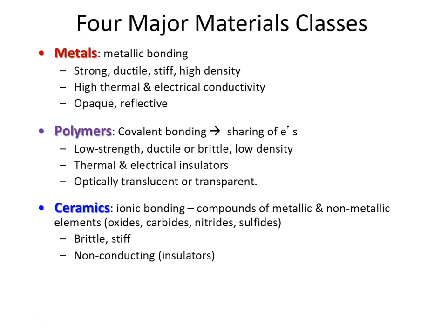They're non-conducting, both electrically and thermally. And it's not shown on this slide, but one of their greatest attributes is very high thermal resistance. So not only do they not decompose or melt at a fairly low temperature, they retain all their other properties at a very high fraction of their melting or decomposition temperature. So if you need something that stays strong, doesn't creep, doesn't lose its properties at high temperature, especially over time, ceramics are a great choice.